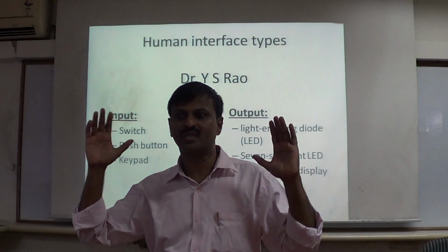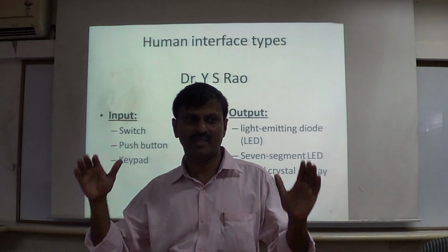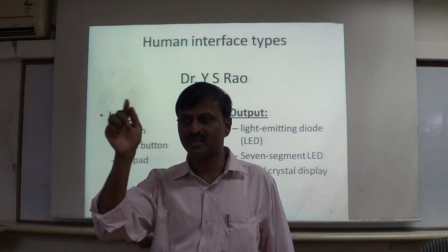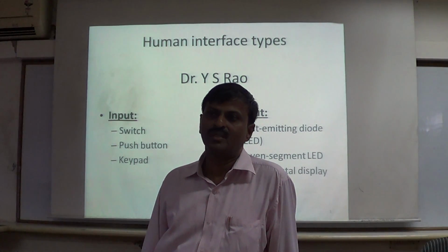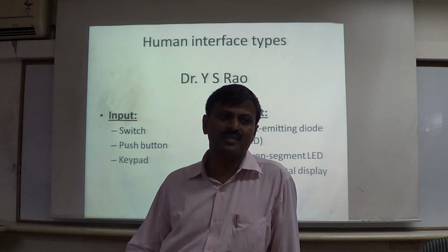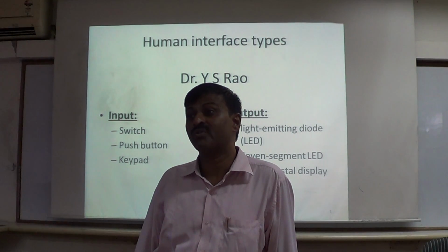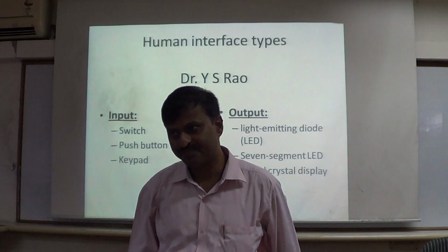All these mirrors are mounted in a parabolic shape, and then the dish will focus the sun rays in a 300 mm radius. So at that spot in the 300 mm radius, if you measure the temperature, it will be around 1200 degrees centigrade when all the rays are focused.